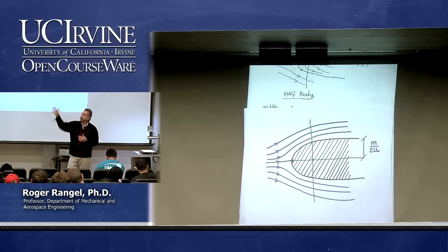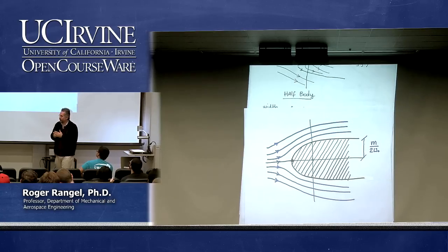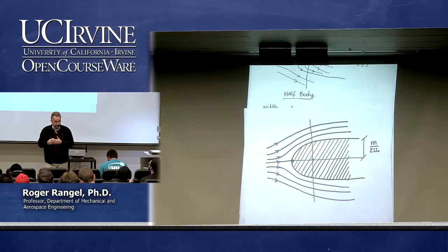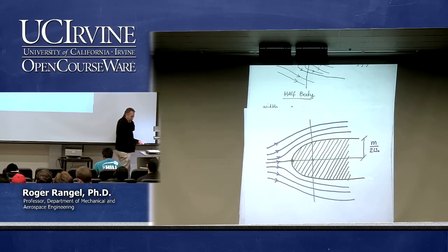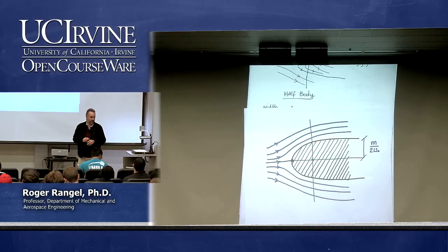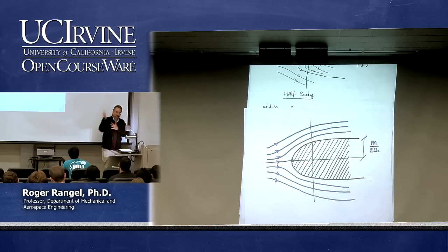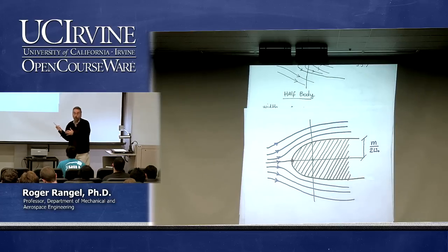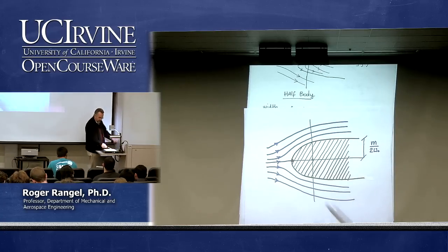So in the real world, if I put an object like that in a fluid that has viscosity, what would happen at the wall, near the wall? What would be created near that wall? Rotation, vorticity, right? So this flow is irrotational. So the only way to retain the condition that the flow be irrotational is if we assume that it's inviscid. That's why when we look at potential flows, most of the time we make the connection: well, it's irrotational, and if I have a wall, then it has to be inviscid, otherwise there would be rotation.